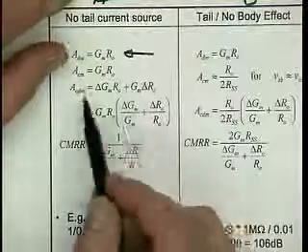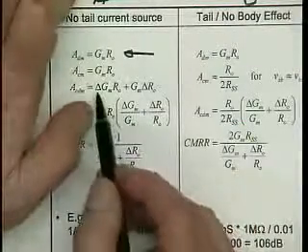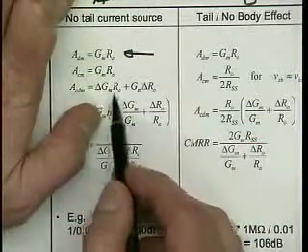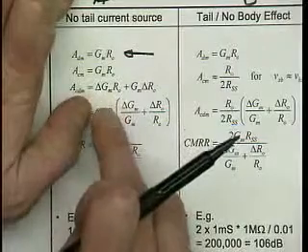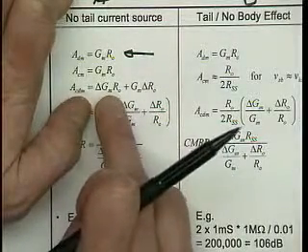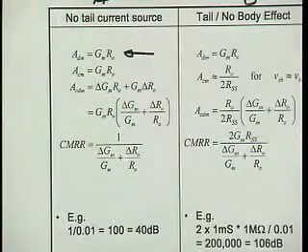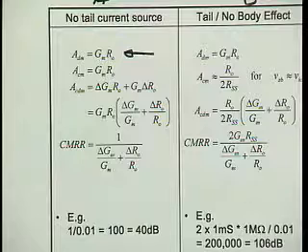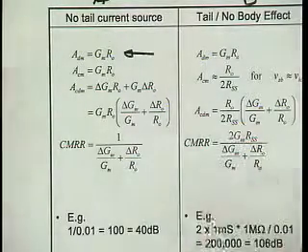So basically what I'm saying is that my input common mode voltage produces a current of delta GM, that is the mismatch current flowing into the two load resistors, and that produces then a voltage delta V out at the output that is equal to this mismatch current multiplied with the average load resistor, the nominal value of the load resistor that I call R out.